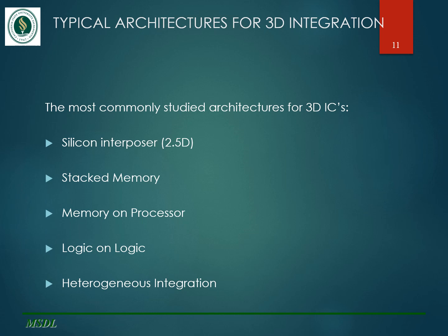Memory on processor architecture. This has the ability to stack high density DRAM on top of the processor, which is extremely valuable for applications. By minimizing the physical distance between the two communicating ICs, the losses in the chip-to-chip link can be minimized.